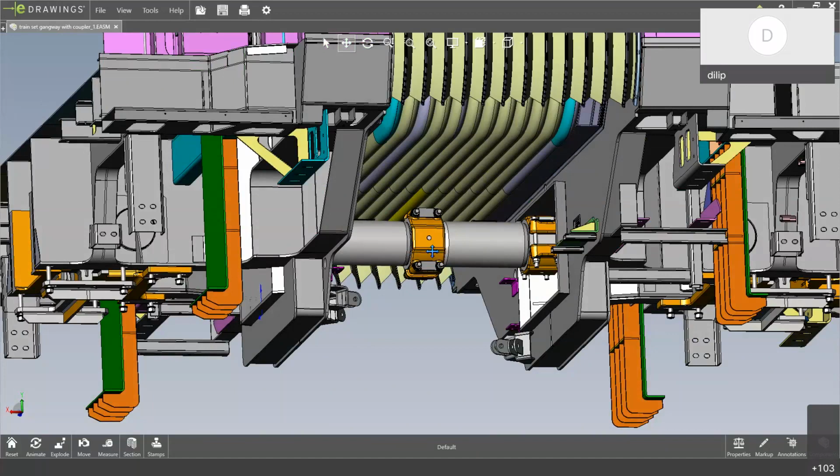And moreover, in regular CBC coupler, because it has to open and close easily, there is a requirement of clearances. Even though we say tight lock CBC coupler and all, some clearances are anyhow required so that it will enable quick coupling and uncoupling. So that will result in a jerk, the passengers experiencing jerk. Whereas in this semi-permanent coupler, these two couplers, the flanges are joined together and they are fastened. So the chance of jerk is very less.